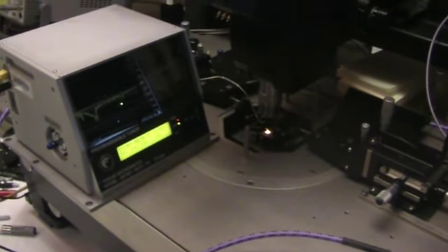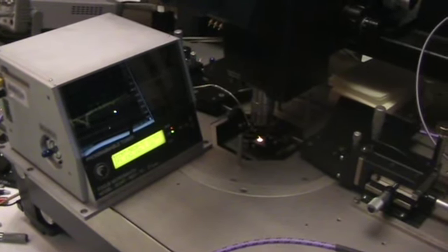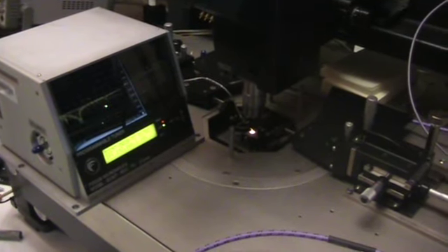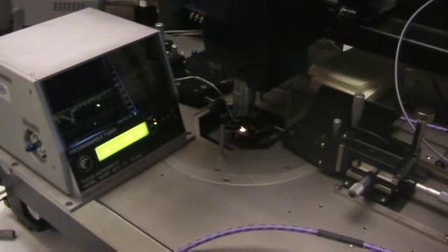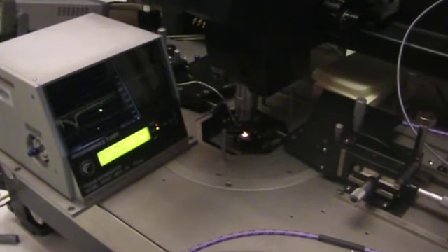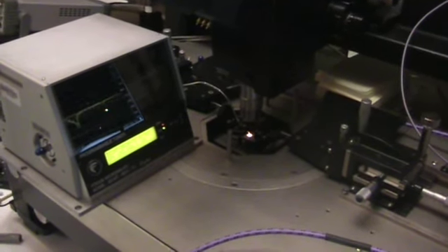Now this particular tuner has a crossover frequency of 10.3 gigahertz, so the measurement bands need to be split up accordingly. We will calibrate and measure in blocks from 2 to 10 gigahertz and then 10 to 26 gigahertz. For this demonstration, we will omit a third band, which normally runs from 27 to 40 or 50 gigahertz when the devices allow you to measure that high.